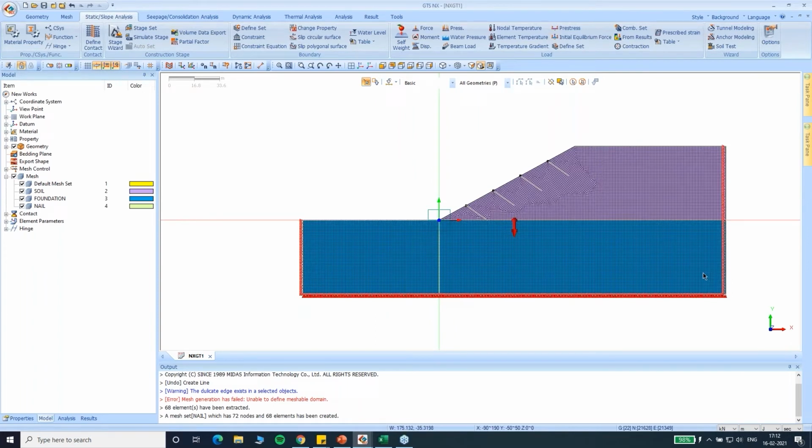So this is how the finite element model is being created. So the steps being geometry, materials, meshing, loading, boundary conditions, then analysis. Well, it's also very subjective. You can also create the material properties before building the geometry. It completely depends on how you want to try it.